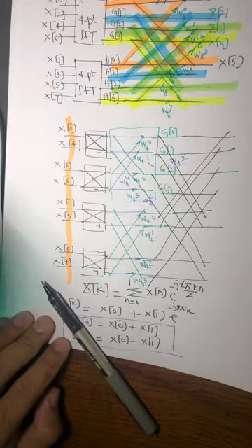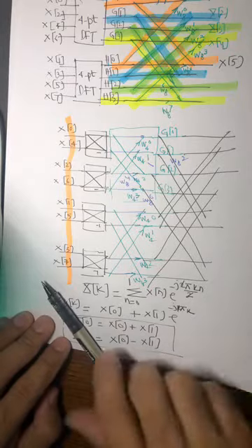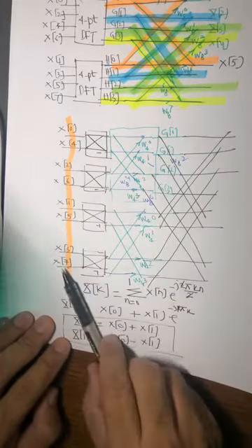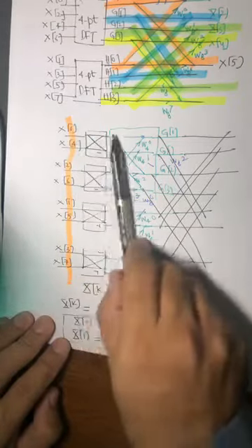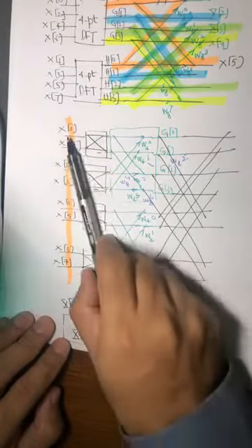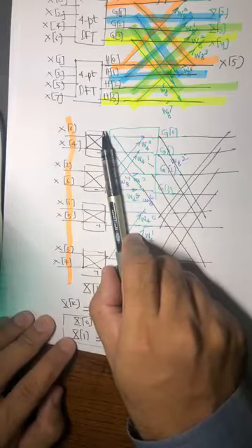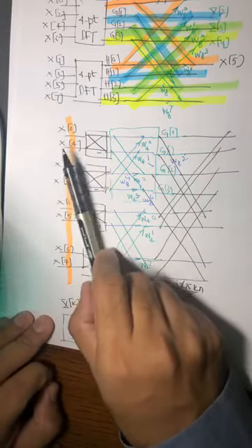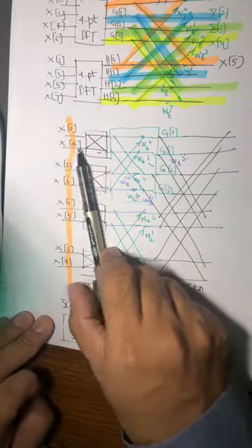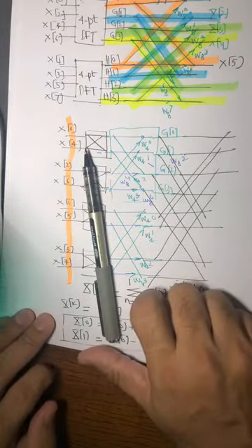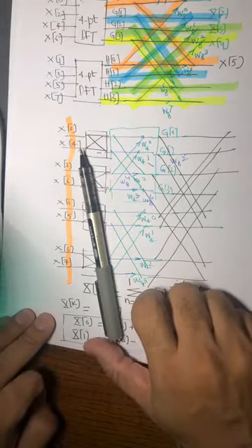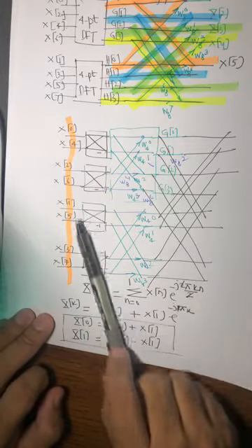It is not that simple, because if you end up spending a lot of time calculating the indices and then using them to do the two-point DFTs, then there is no point in all the savings you have here, because you have to calculate the indices to fetch the data. So one of the challenges of the fast Fourier transform is to somehow generate these indices.